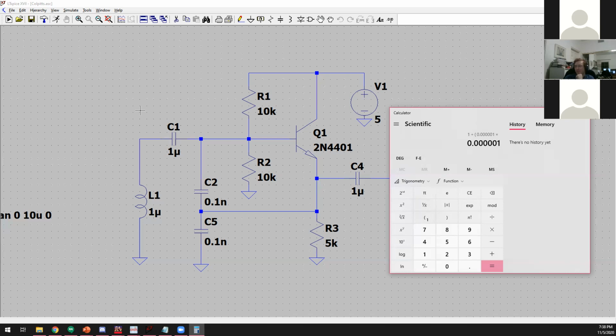Well, you got 2 capacitors in series, which means the overall capacitance is smaller, right? Yes. So 0.1 in series with 0.1 nanofarads is 0.05. Cool. Okay, so I'm not doing this mental math, man. You have the calculator. I mean, you just divide by 2, but okay.